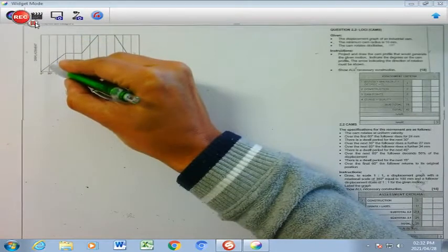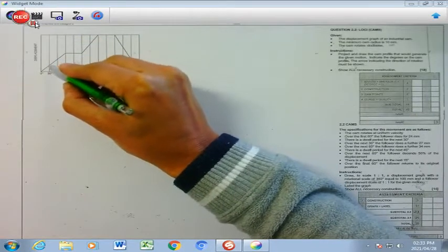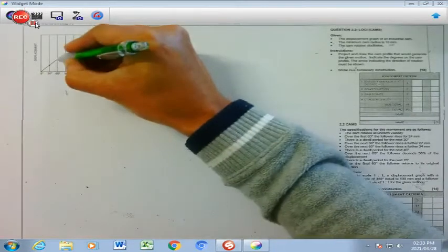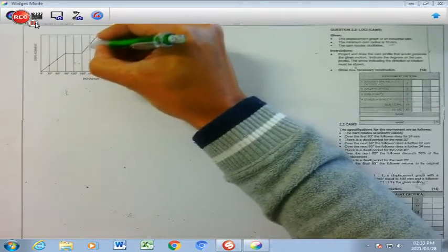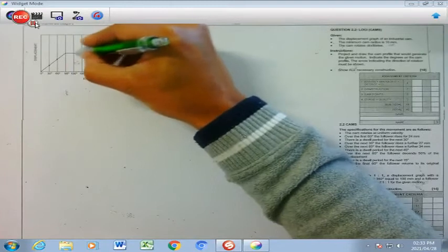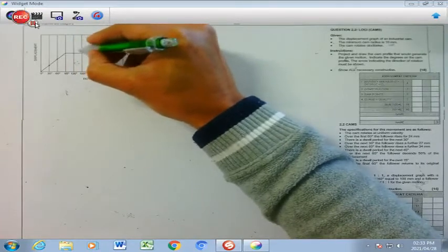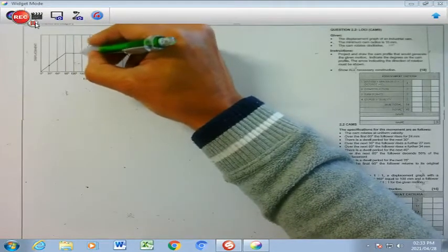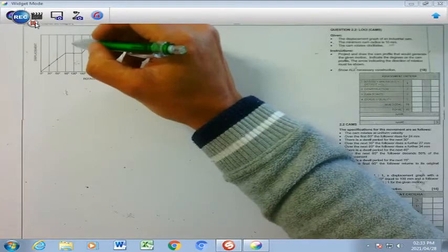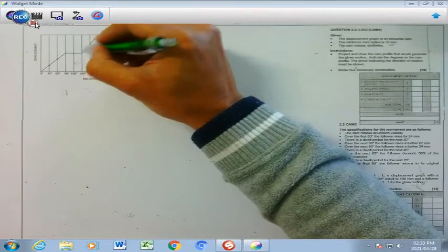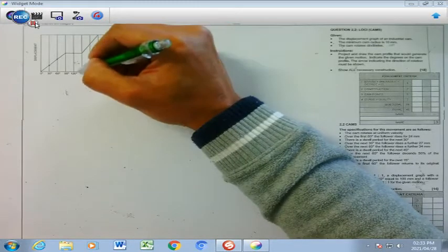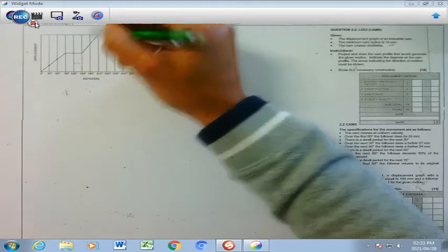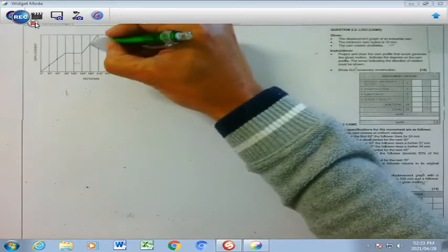The line crosses at that specific point through the degree line, and I'm going to plot each of these points very clearly. Here you can see that it doesn't go up or down, so it is stationed or it idles. Those specific words, synonyms, are used for when the cam displacement diagram does not move up or down, or if there's not any movement. There is my next specific point.